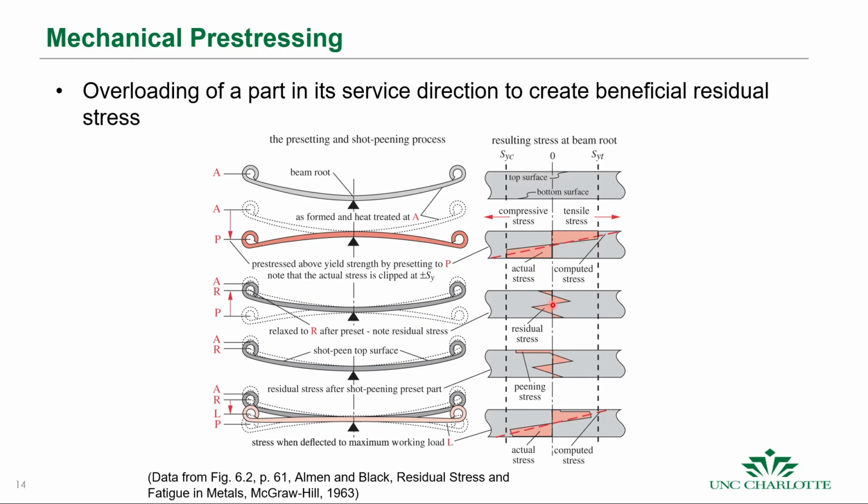we have this state of stress where we now have compressive stresses at the surface, tensile stresses at this surface, and then compressive stresses below the surface, and then some tensile stress here, which is undesirable at the bottom surface. Okay, so then what's done is the top surface is shot peened. By shot peening, these compressive residual stresses are introduced, like we saw.